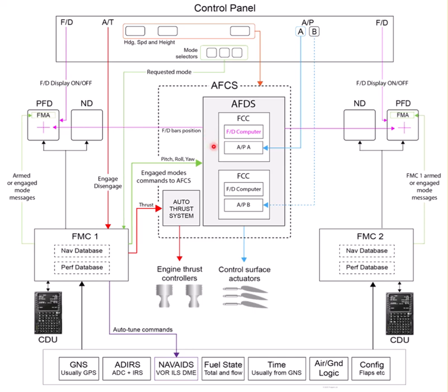And what will happen during that vertical path climb would be that the FMC would be telling the auto throttle system, oh, by the way, we're in VNAV path, can you look after the speed for me, please? And that speed would be coming from the FMC. So whenever you're in LNAV and VNAV, quite often you'll find that the speed window is blank, simply because the speed is not coming from the mode control panel, it's coming from the FMC.